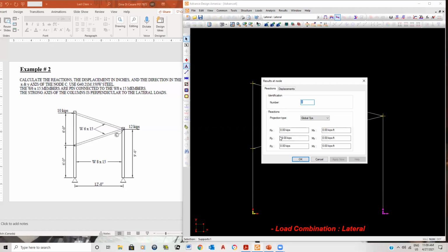Okay, like I said, when you put your values, guys, if it happens to be a fixed reaction, I don't recommend you look at it graphically. 9 times out of 10 people always forget the moments. And I think who did that last for the assignment? Who forgot the moments? I don't remember, but I know somebody forgot to indicate the moment, and that's because they were only reading. Ariane, I think it was you. Am I correct? On your assignment, you forgot to show the moments, and I wanted to highlight that.